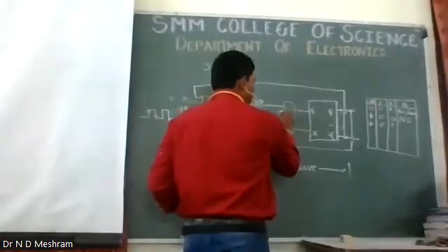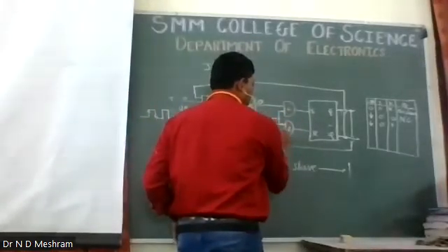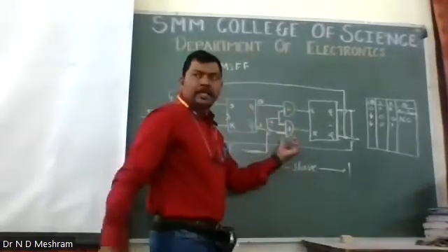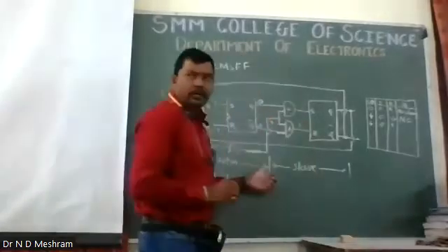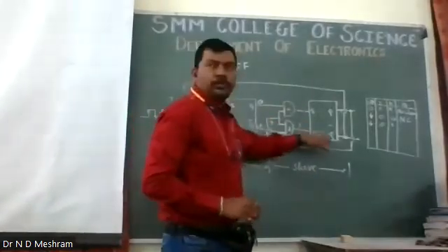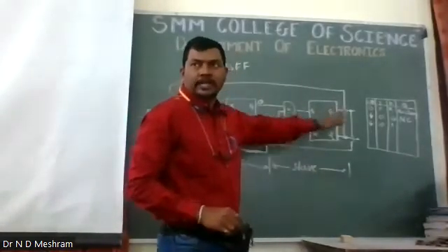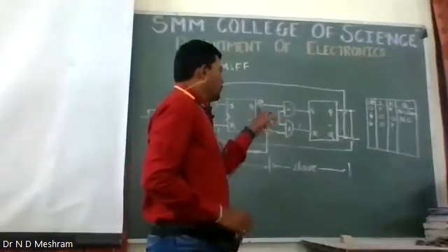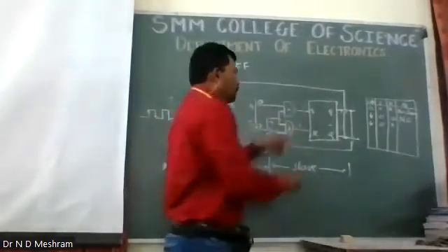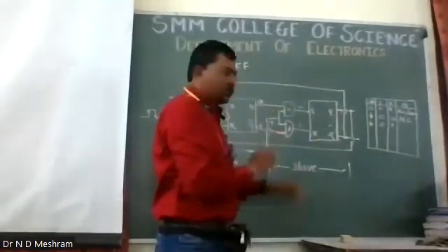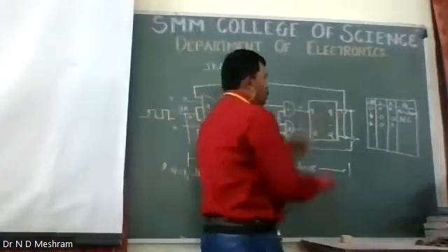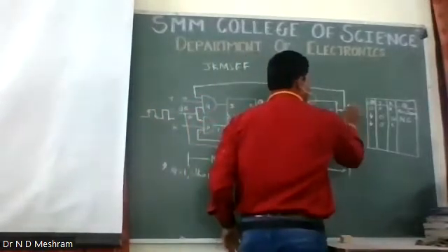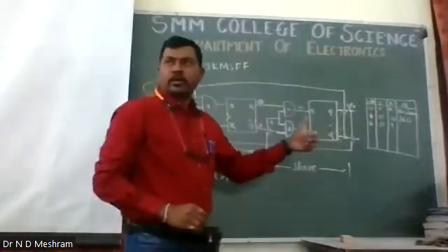So gate D, I am writing here gate D will be enabled, the output will become 1 of B and it is given to the reset terminal of the second slave flip-flop, and since it is 0, the output of C will be 0. So as soon as reset is 0, the output of Q, which was earlier equal to 1, is now going to shift to 0.